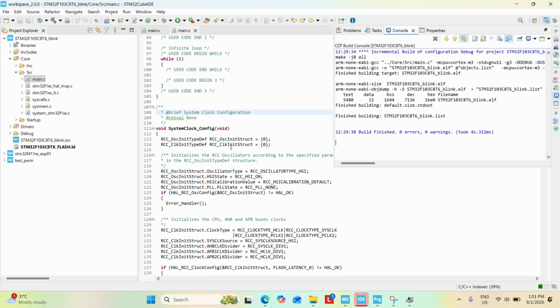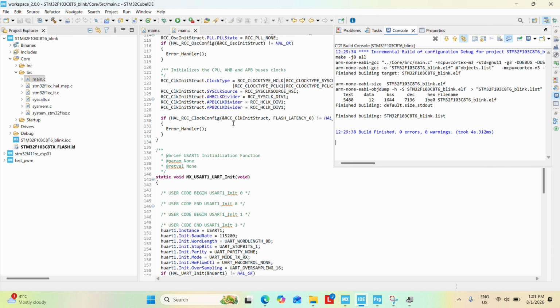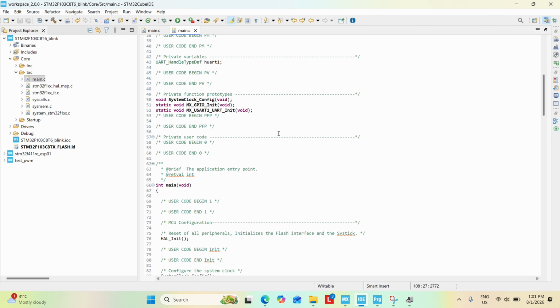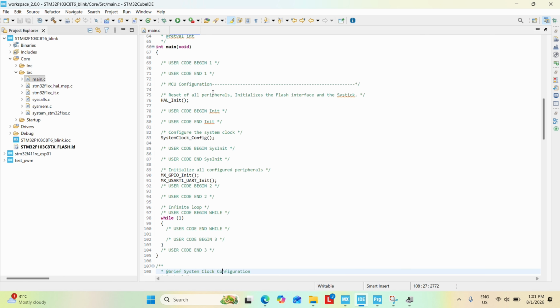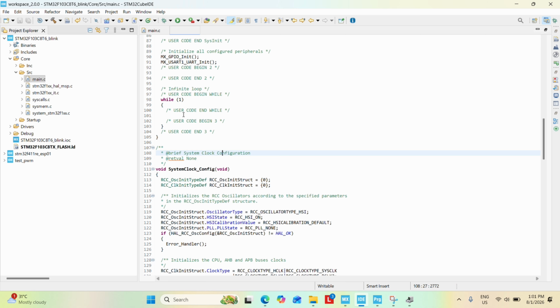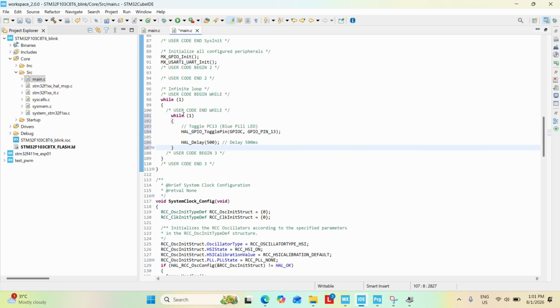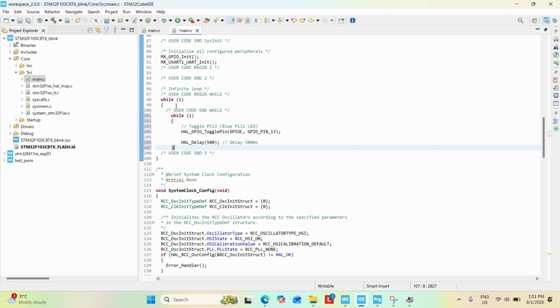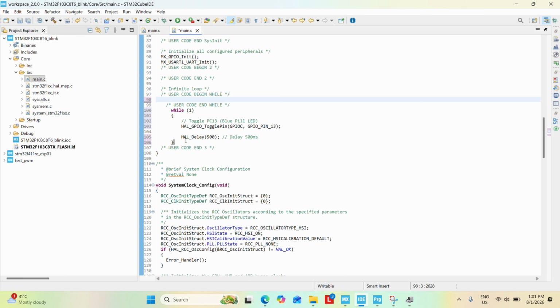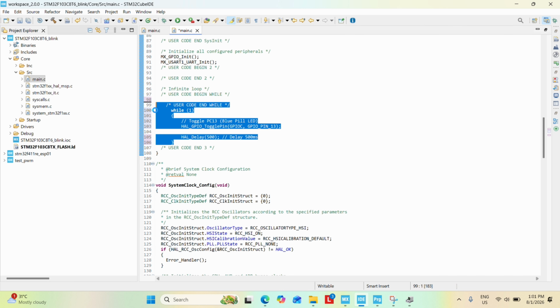Okay, the next stage. This is our second stage, and we can go ahead and open main.c. Okay, this one is different, because it generated new code. So we have here a toggle of the LED pin, which is GPIO pin 13. Yeah, and let's go back.